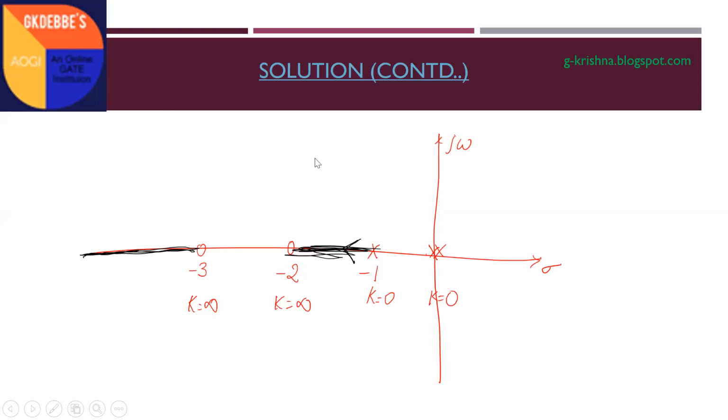But whenever they break away, the root locus will compulsorily cut the imaginary axis one time. That's what you should know. Therefore, I'll show it with a different color. For these two poles, one breaks away and they break in. Whenever they break away, they'll cut the imaginary axis, and that value will definitely be j omega PC only. They'll break away like this, and one more branch will go like this.